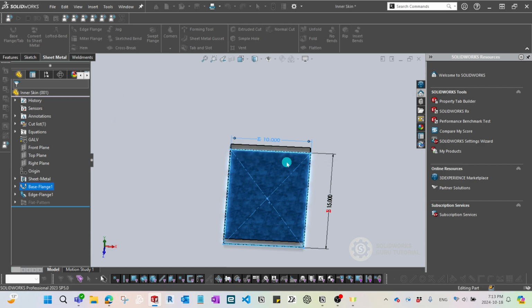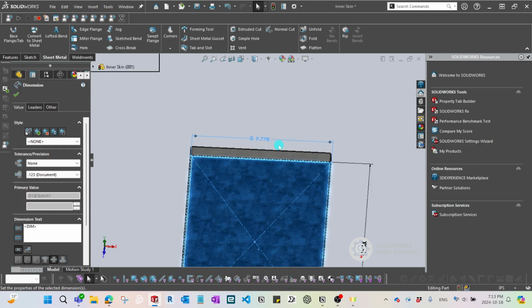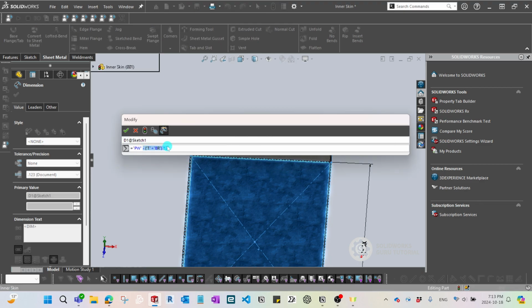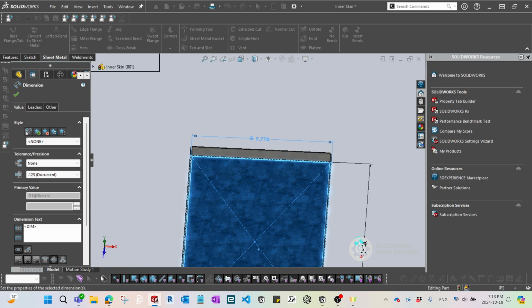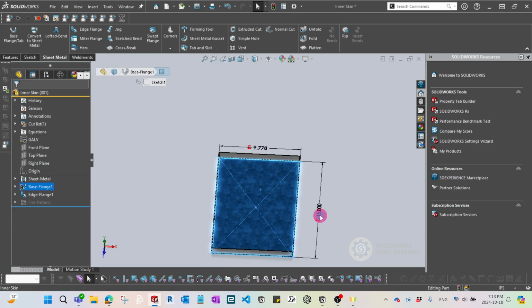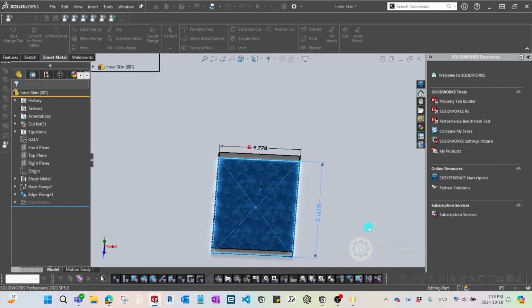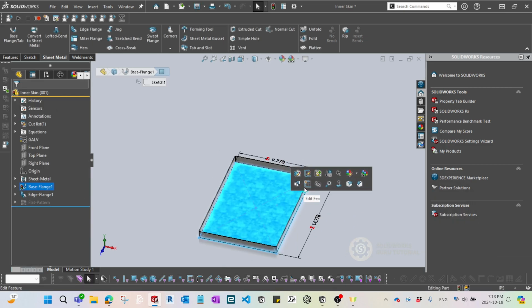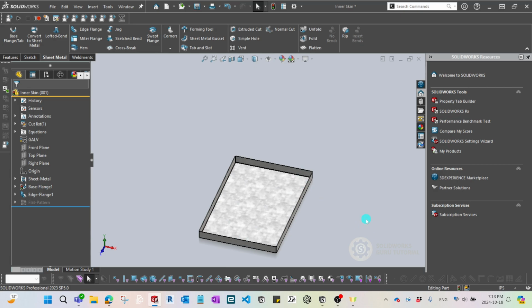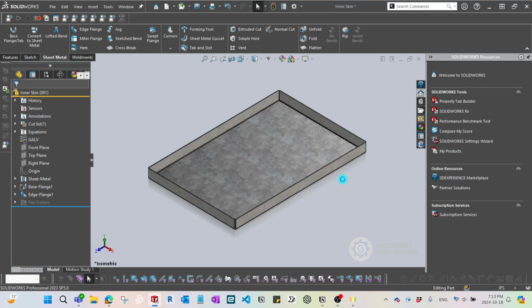Okay, what that does is subtract 2 times the thickness and 2 times the bend radius. I'm going to copy this chunk because we'll be using it for this panel length. So I'll click this equals mark and paste it. What that does is subtract both sides, so this is going to work properly.